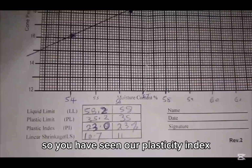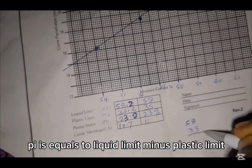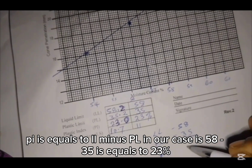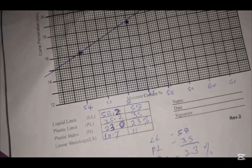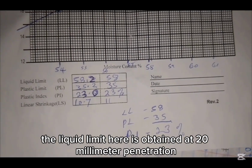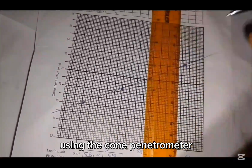So we have seen our plasticity index, PI is equal to liquid limit minus plastic limit. PI is equal to LL minus PL. In our case, this is 58 minus 35 is equal to 23%. Unlike the Casagrande method, the liquid limit here is obtained at 20 millimeter penetration using the cone penetrometer.